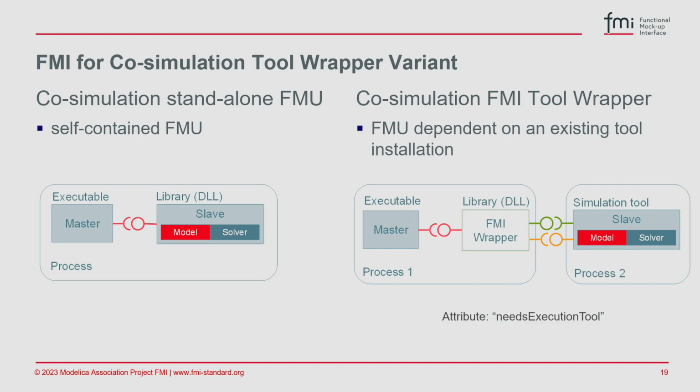We will also have a slide on this. It's beyond the technical interface. So it's a good practice to put information about this in the documentation. There's a documentation folder inside the FMU, so that if a user gets it, importing tools should also provide a possibility to display the documentation. Then you can write, okay, this FMU requires a certain license, but this is outside of the scope of the FMI interface standard. All right, thank you.